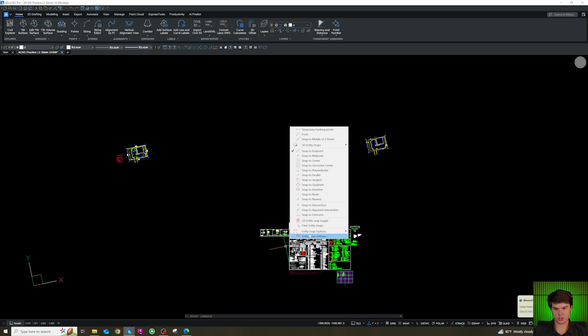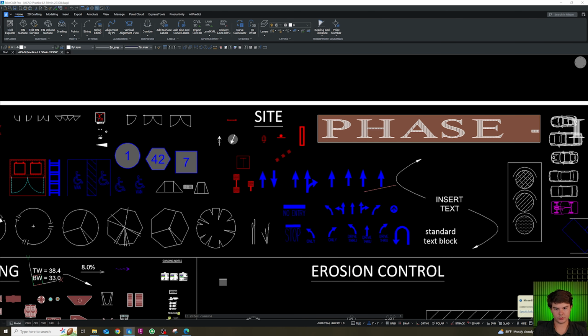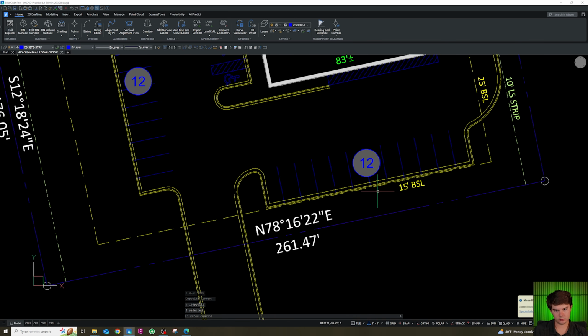We'll do some directional arrows for traffic. So I'll copy this UCS World, copy, and then I'm going to paste it, UCS Site. And these are going to be two-way drive aisles. So always make sure our right side is straight.